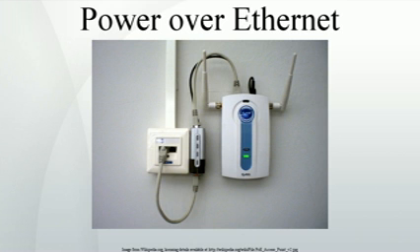Power device. A powered device, PD, is a device powered by a PSE and thus consumes energy. Examples include wireless access points, IP phones, and IP cameras. Many powered devices have an auxiliary power connector for an optional, external, power supply. Depending on the PD design, some, none, or all power can be supplied from the auxiliary port, with the auxiliary port sometimes acting as backup power in case of PoE-supplied power failure.